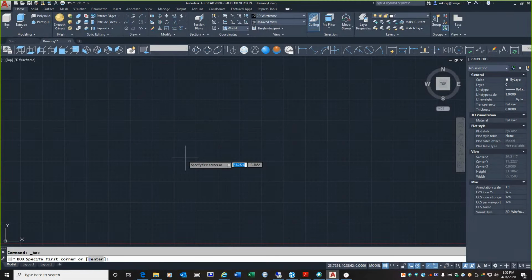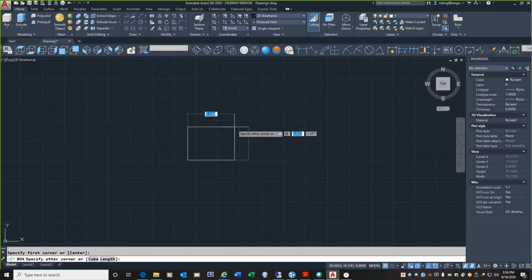What this will start out by doing is as if we're drawing a rectangle. It wants one corner, and we specify the other corner. So let's just click to locate a corner, move your mouse up and to the right, and let's say at 5, 3, and then hit enter. Despite the fact that the rectangle looks like it's shooting off to the left, just type in @5,3, enter. And normally we'd be done, but if you look at your command prompt, now it's asking for the height, because this is now 3D. Let's say we'll go 3 inches tall. So type in 3, enter.